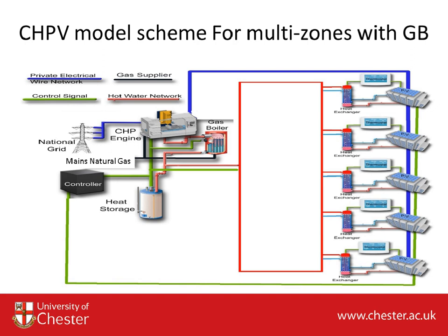One very important point is that it's very economically damaging to size your CHP engine to be the full capacity of electricity that you need, or the full heat capacity. So you need the national grid for peak demand times for sure, and you also need the gas boiler to be available for when there isn't sufficient heat available from either the thermal store or the CHP engine, or combined.